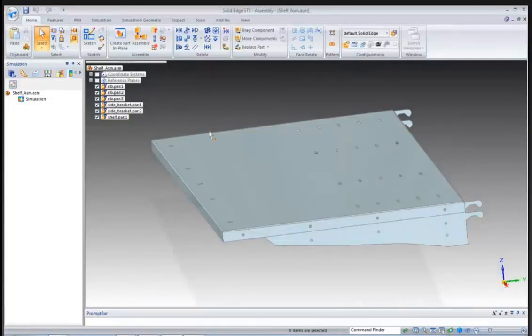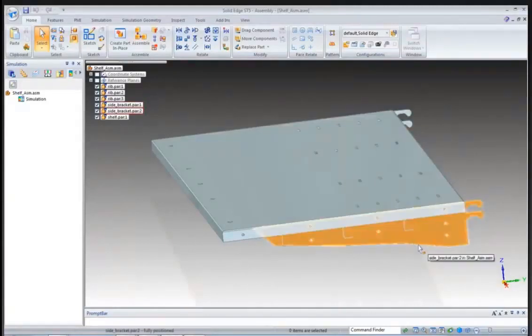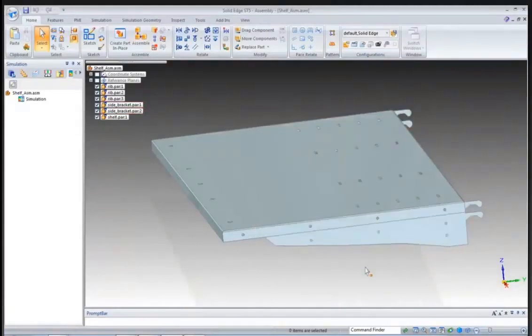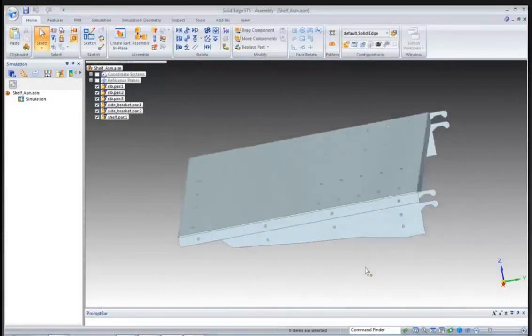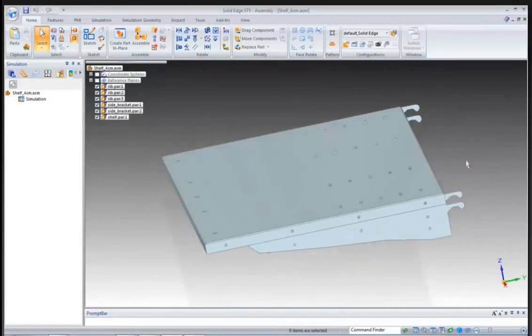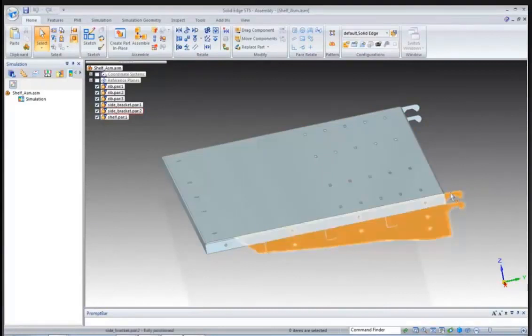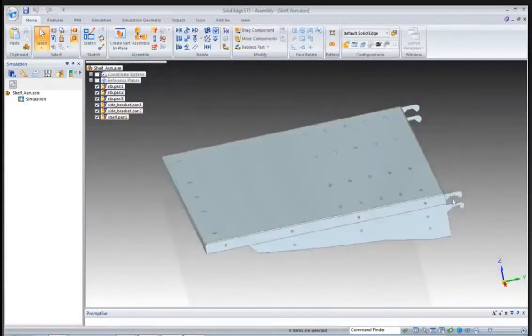So our area of interest is here, and because our area of interest is here, there's a principle that says that we can make simplifications as long as they're not close to our area of interest. So we're going to say that we can simplify by not including what this is hooked into, which will greatly reduce our solve time. Now, we've got to think about how this is hooked in. So if you think about it, it's kind of hooked into a receiver there, and these horizontal lines here, they can't move in this direction because it's hooked into the receiver, and same for over here.